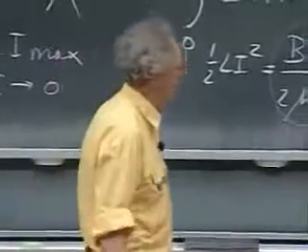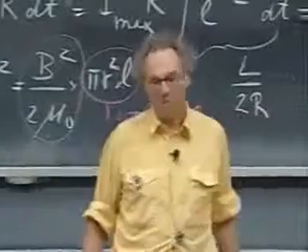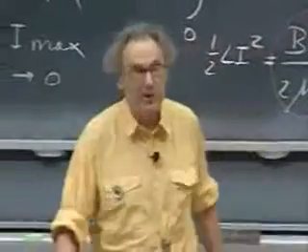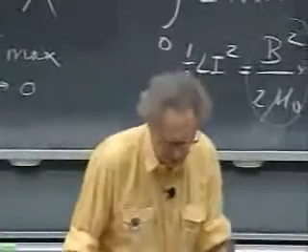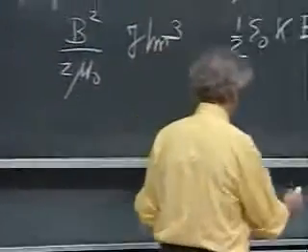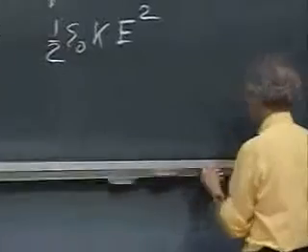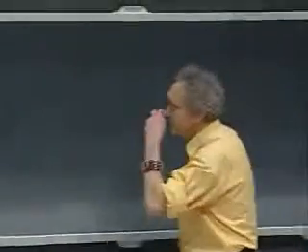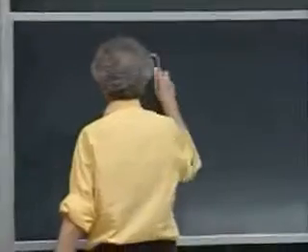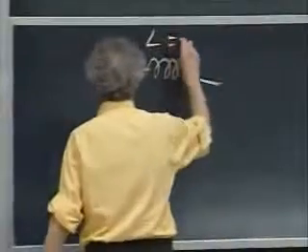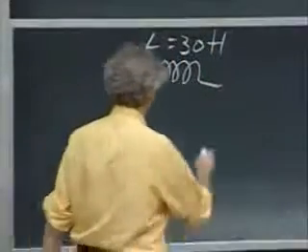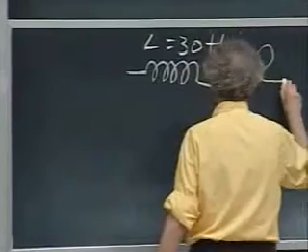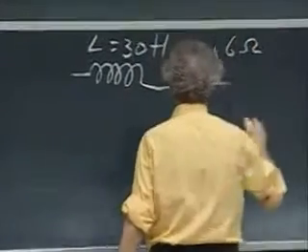I can make you see, in a quite dramatic way, how strong self-inductances can fight their own current. And the way I'm going to do that is with a setup there, whereby I have a 12-volt car battery, and I have 2 light bulbs. I have here an enormous self-inductance, L, 30 Henry. We will learn later in the course how you make such a high self-inductance. And then here is a light bulb. The light bulb has a resistance of 6 ohm.